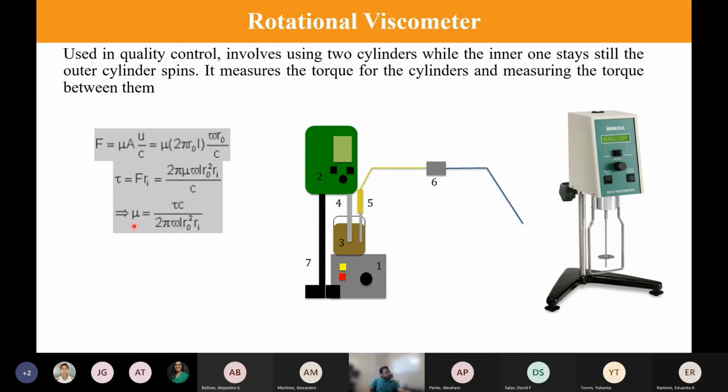I'm not going to derive that equation, but whatever I told you so far physically is what's being written mathematically in this equation. And you can see that it has a term R naught. This is the diameter of this plate. So the more diameter it has, the more fluid is going to be in contact with the surface, and the more force you need, right?